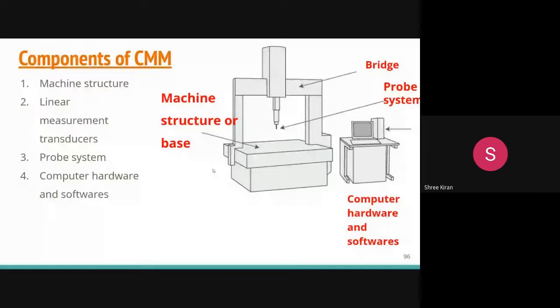The movement of the X, Y, Z axes fully describes the measuring envelope. Each axis is fitted with a linear measurement transducer. Whether it's linear, inclined or vertical, whatever the axis, it is always fitted with a linear measurement transducer for positional feedback and digital display.